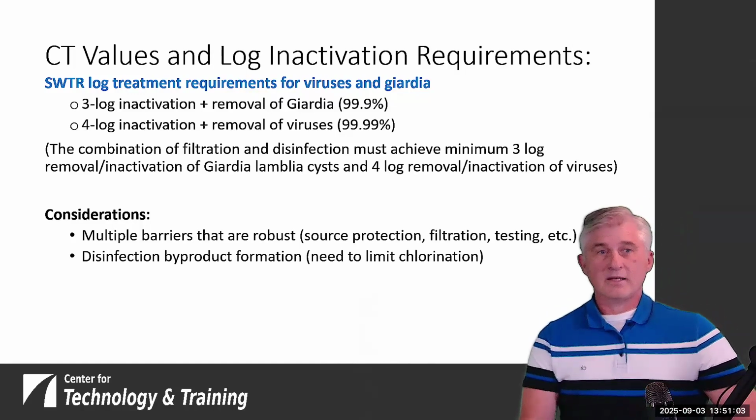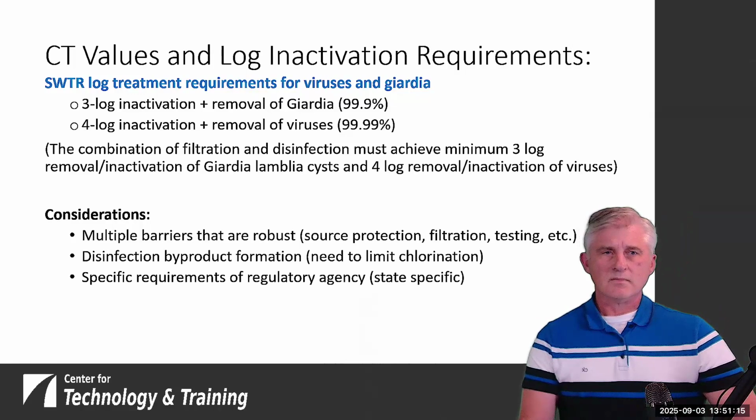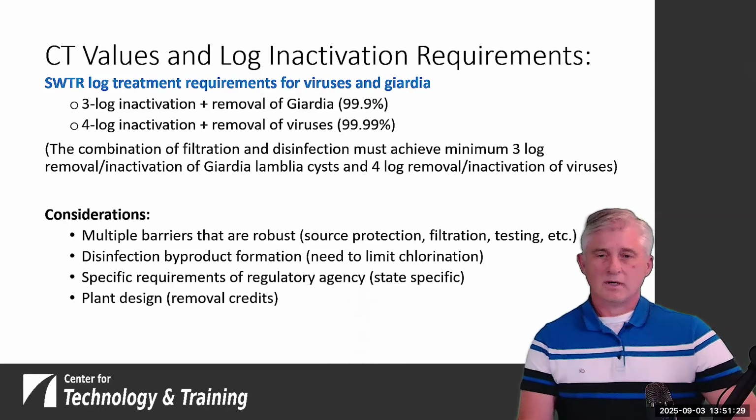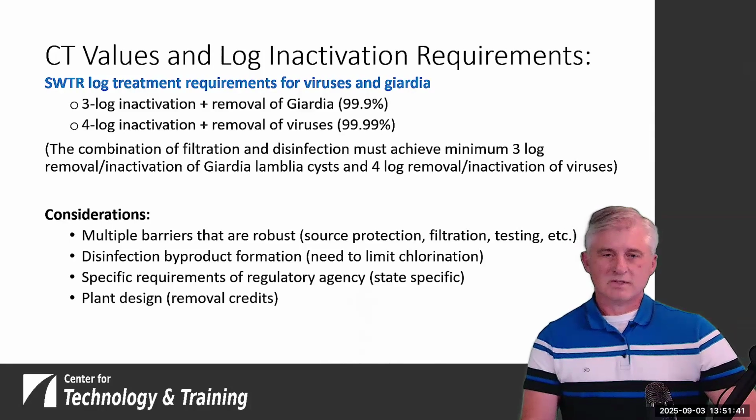Chlorination at high levels is not necessarily the answer to all of our problems, because high levels of chlorination are going to increase our disinfection byproducts. And then every state or regulatory agency has its own specific requirements, so we have to take that into consideration. And then our plant design will result in removal credits. Those removal credits are determined in combination with the Safe Drinking Water Act by our regulatory agencies, whether that's a state or, for the tribes, EPA.